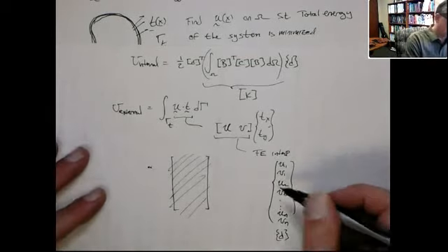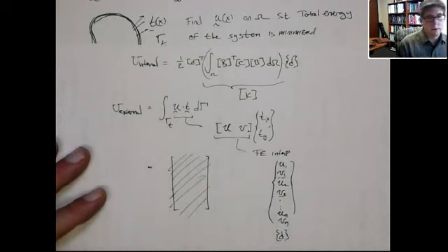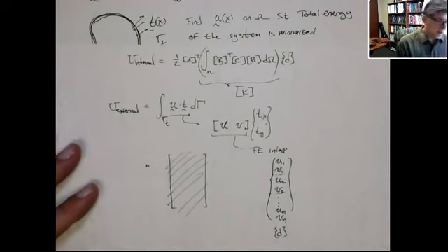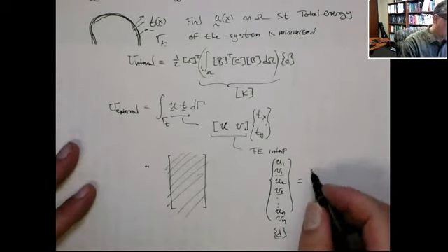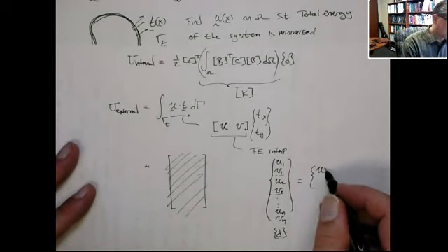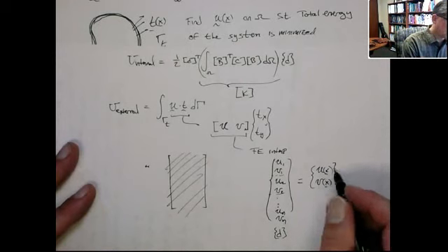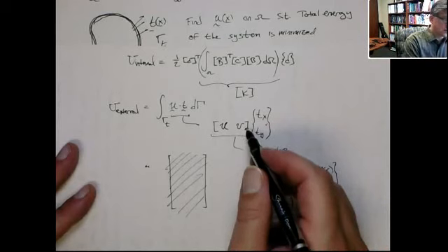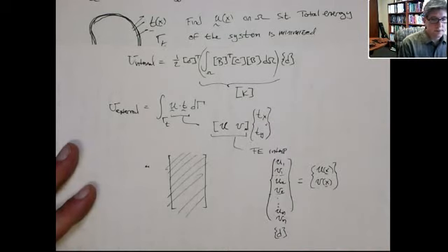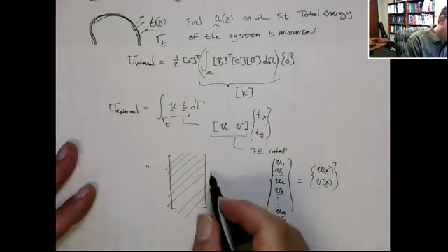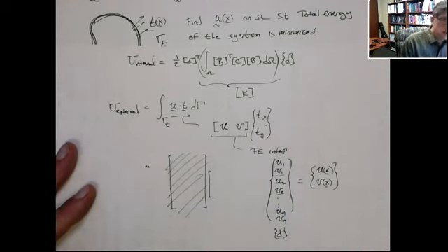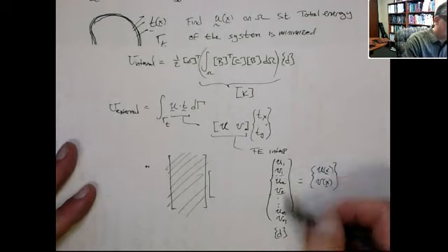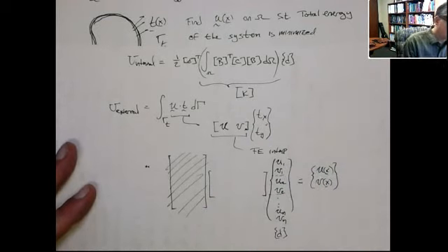And they're usually grouped in this manner, right? By node, and then the degrees of freedom per node, okay? I want to get this to look something like this. I want to get the U displacement and then the V displacement in a column vector, all right? Basically, it's this term transposed, right? Okay, so what matrix has to be multiplied by? Well, it has to be something that has 2 rows and then 2 times n columns, okay?